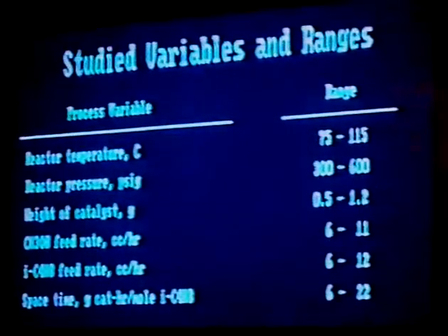Therefore, it becomes equilibrium limited at higher temperatures, and in fact, it becomes equilibrium limited at some very modest temperatures. And so to try to counteract the effect of the temperature limitation, you can increase pressure up to a point, and that point becomes, of course, when you liquefy the reaction product mixture.